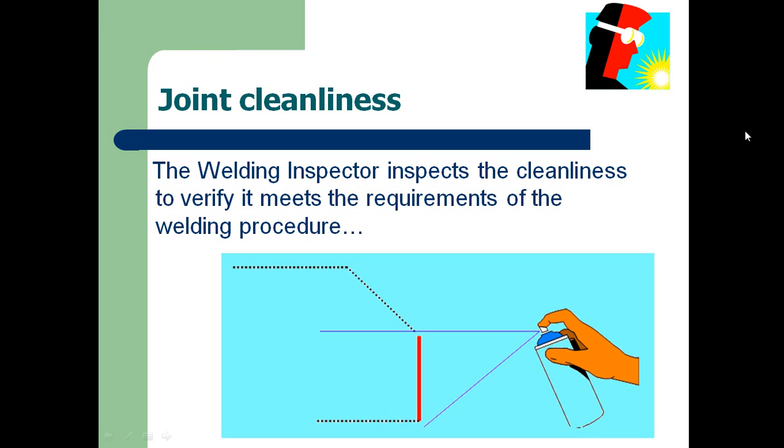The joint cleaning, to ensure that there is no dust, no grease, nothing, and it's clean to avoid any discontinuities in the weld or any defects.